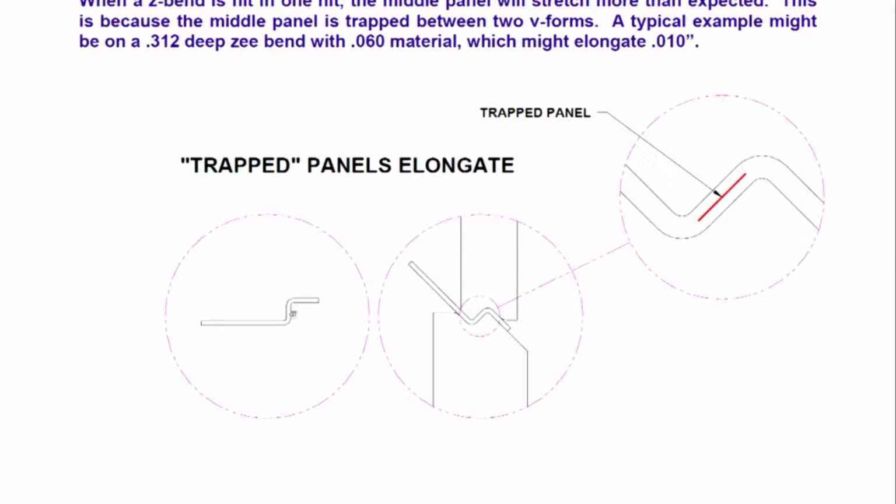This could be the bottom part, this could be the top portion, and between these two the thickness can probably be covered by a gasket, which ensures that there won't be any leakage between the two panels. So, if this were to be the top, there can be a bottom here. For example, a chassis can come here, this could be the top cover, and in the bottom chassis, if I pack the inside surface with a suitable elastomer which is probably stuck on one side, then I add a gasket grease and then push it on top of it, I can make it splash proof. So, if normally water were to enter here, it will not